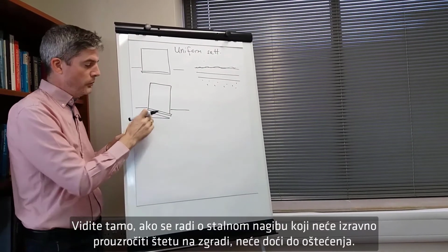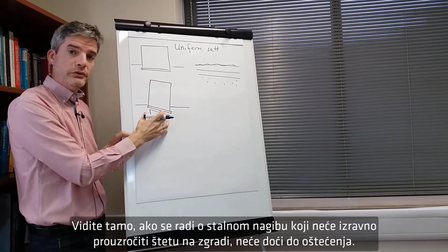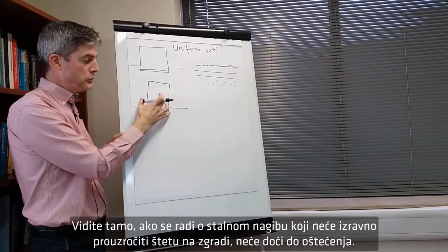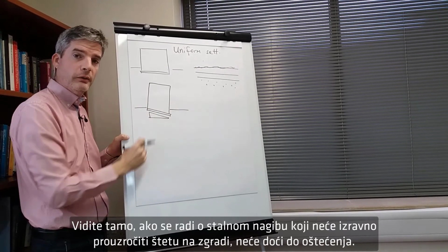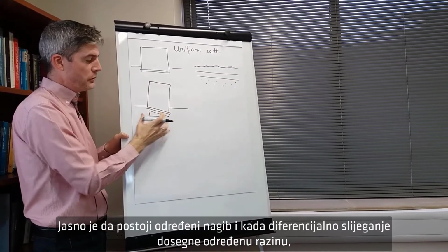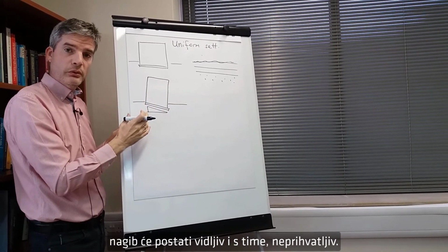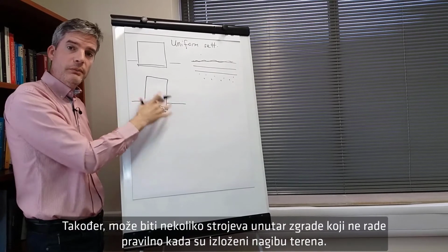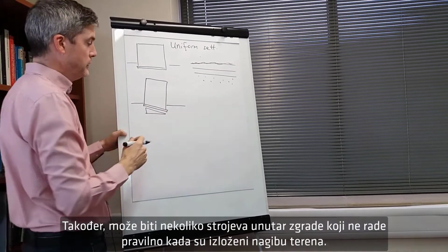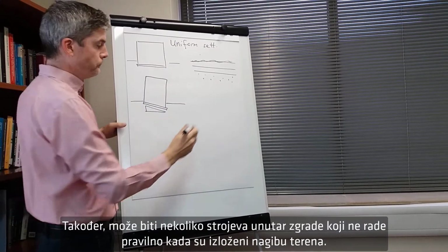But if it is a constant slope, that will not directly cause damage to the building because there's no distress being felt by the building. Clearly there is some tilt, so when the differential settlement gets to a certain level, the tilt will be visible and that will be unacceptable.